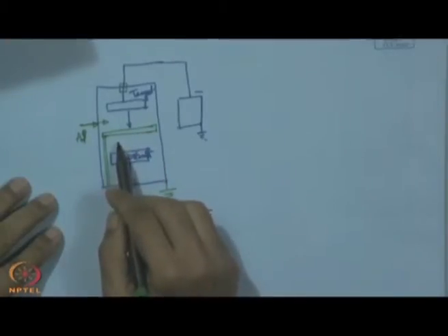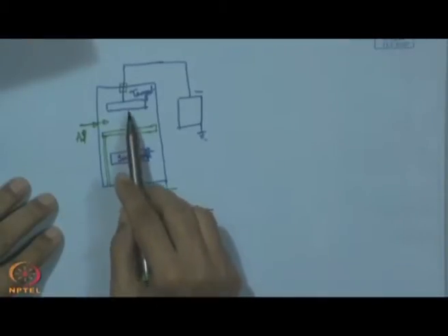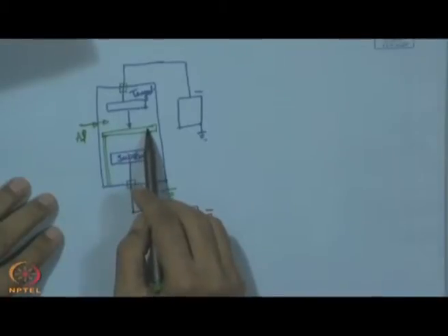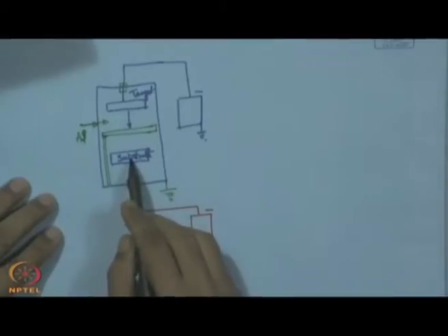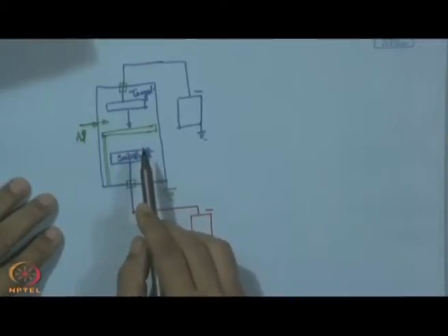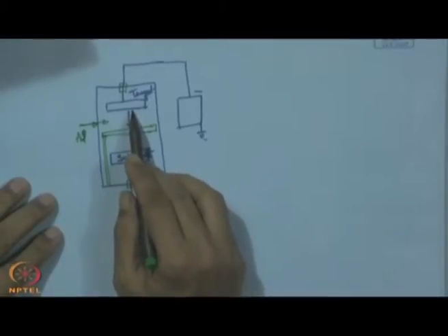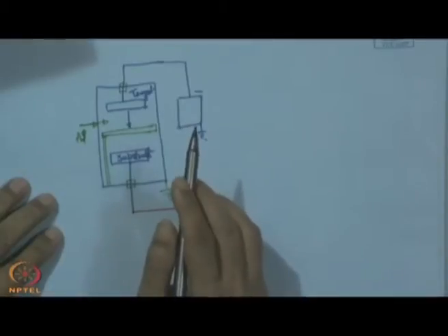At the very beginning, sputtering is done on the top surface and the incoming material is collected from the target. Similarly, it is above the substrate and this material is also collected, and then both are absolutely clean, virgin surfaces. Here these ions are used, and this is more or less what we call ion etching, that means removal of the material.